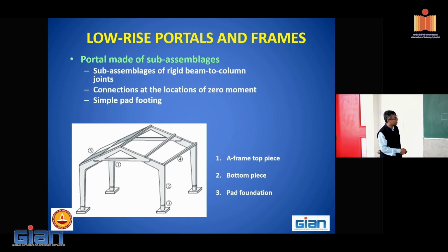The other system, this is what I showed in the figure, A-frames. These A-frames are actually gable frames, which are moment resisting. Here, I do not need a pocket foundation. This is a simple pad foundation. The beam and the rafter have an integrated connection.